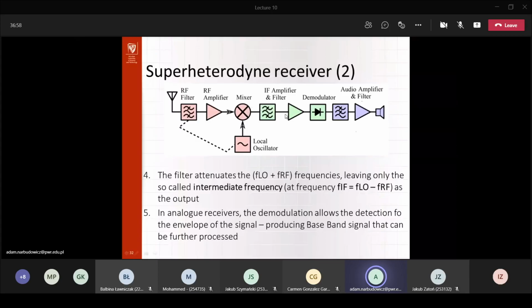So we got our intermediate frequency. Here we once again perform amplification, and even though it's not baseband, it is already a lower frequency signal. So now we can have much more control, and we are more flexible with adding more amplification, and only then does the superheterodyne architecture perform demodulation. This is the final demodulation, which is denoted here using a diode. This is the thing somebody mentioned last week, right? That we just used the diode to capture the envelope.